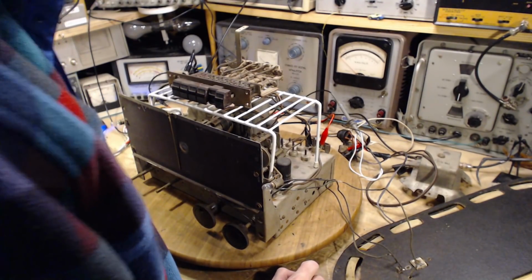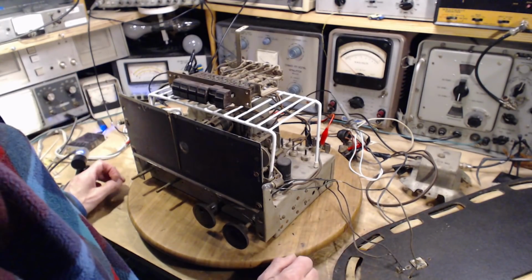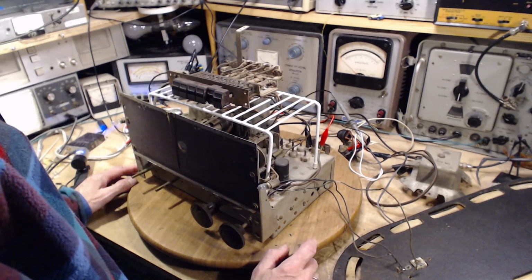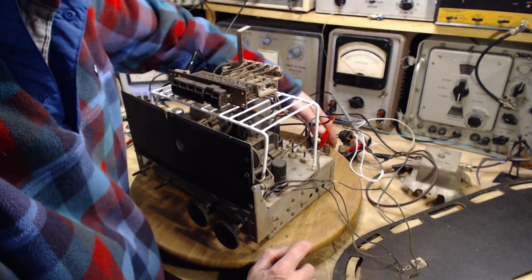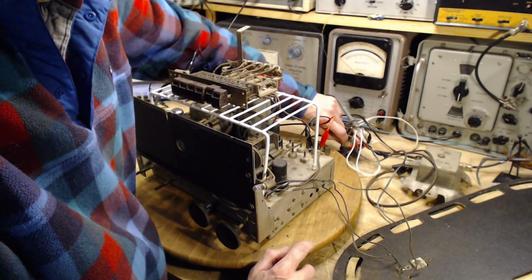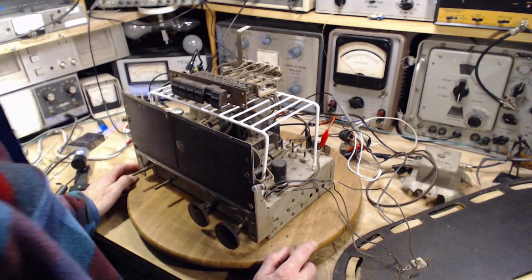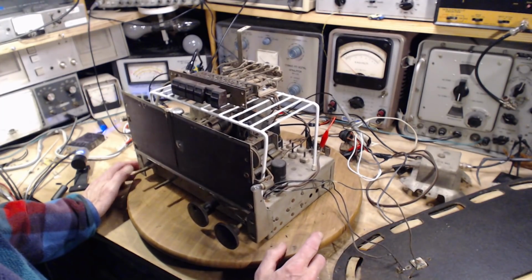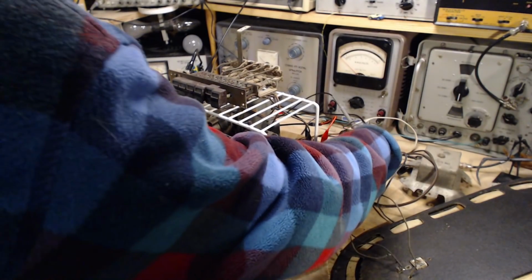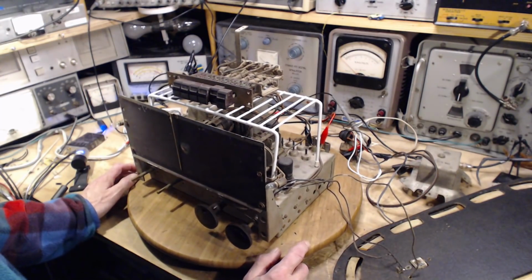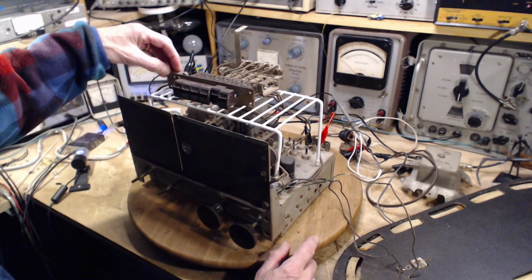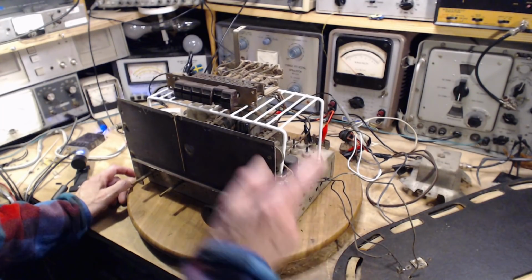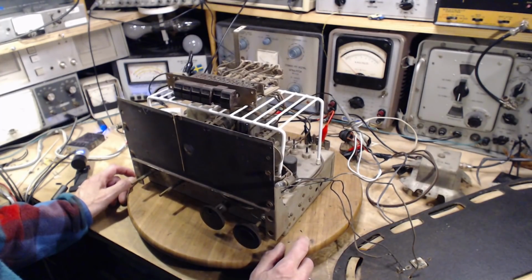And that's an interesting question too. The speaker that has come with this radio is not the original, and my guess is it's an 8 ohm speaker. Is that going to play a role? I don't know. I don't know for sure that this is the correct output transformer that showed up. Could be from some other radio or speaker. I don't know. So even this could be implicated. Who knows? So we'll start by just feeding in the audio signal that only goes through the last 2 tubes, and we'll see what we get out of it. But first we listen to the radio.